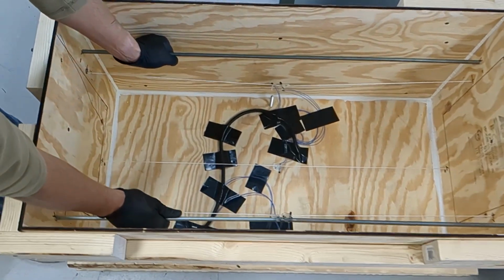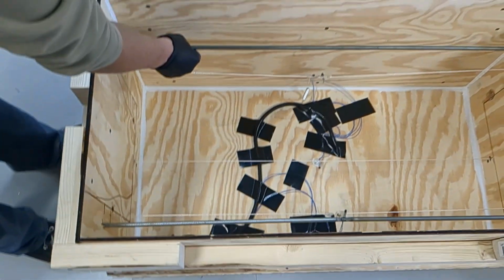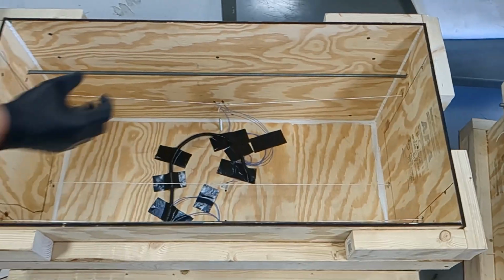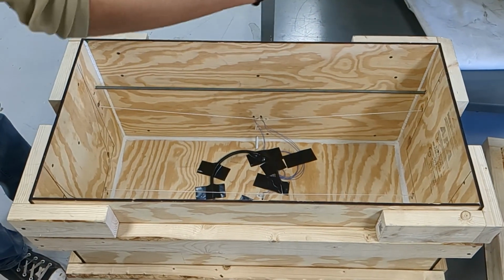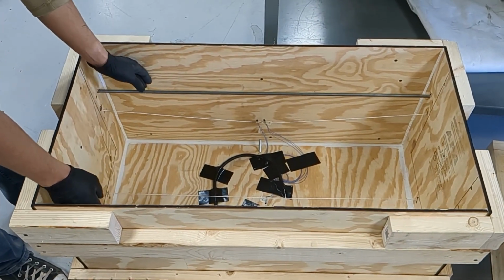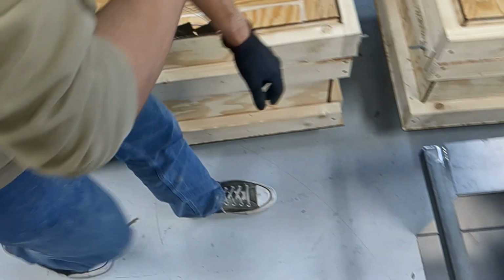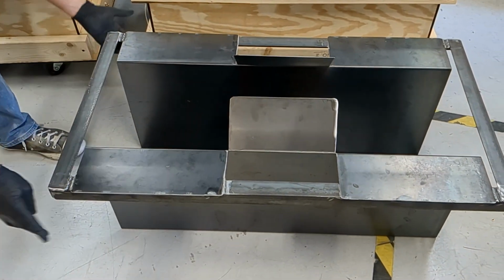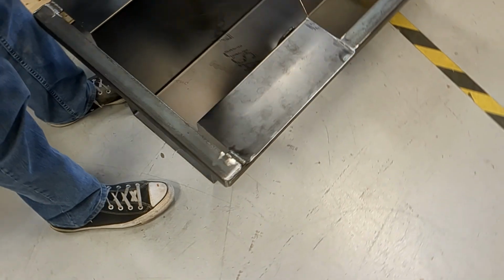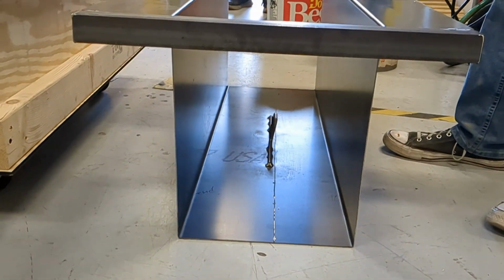And then we have these 2 threaded rods that are going to act like rebar. Once we put the inserts in, we're going to tighten those down so it kind of pre-tensions or pre-compresses the concrete a little bit. We've got these inserts here made out of metal. These are going to help us form the shape of our walls. And we've got these flaps here so we can pour concrete through them and get all that in there.